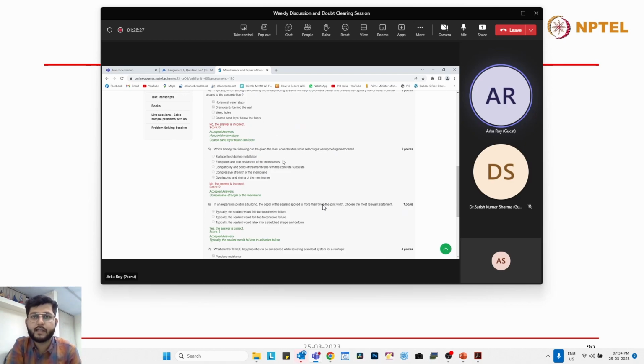See, I'll tell you that you have to prepare a concrete mix design, and there should be no honeycombing at the structural element. Yes, sir. So would you be considering that in your mix design? Is there a parameter that you can tweak to get ahead of this honeycombing? No, honeycombing is actually the workmanship. Workmanship, right? Yes, sir. That is what is being asked in this way.